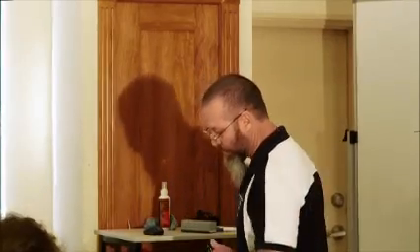You quite simply, when you find out it's a nominal connection, go to table 9.4 on the opposite page there. And what you'll see with table 9.4, it's actually broken up into 3 different areas. One is floor framing, one is wall framing, and when you go over the page is roof framing. So if you wanted to connect your top plate, a rafter top plate, obviously that's a roof framing connection, you just go to the roof framing section on page 170 or 168, depending on your book. You see there where it says rafters to plates or ring beams, coupled roofs.